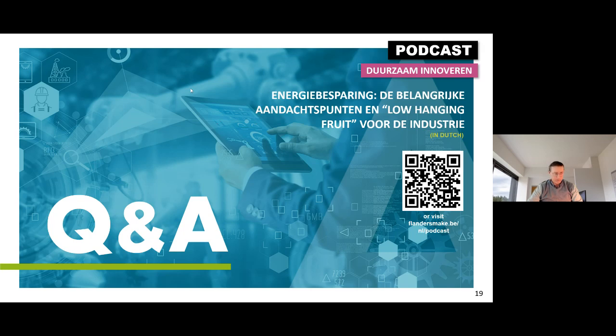I don't know, Jeroen, if you want to add something. I believe that's indeed the best place to start. I think in general, finding the optimal set point of your motor, your drive, and your pump is going to be key here. To consider also the efficiency of the pump, because that's typically where even more losses are.